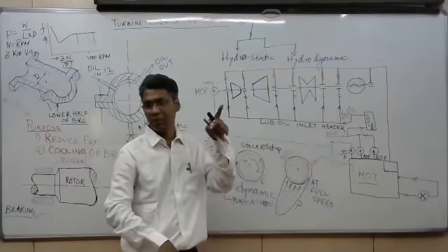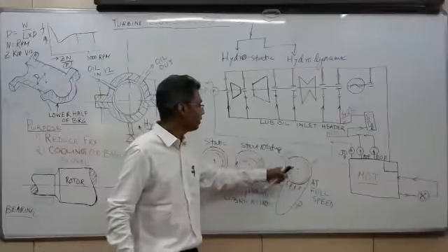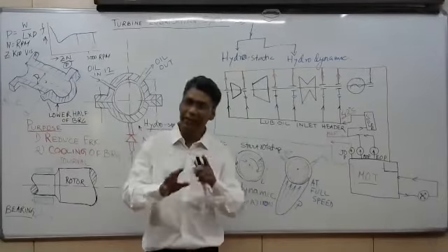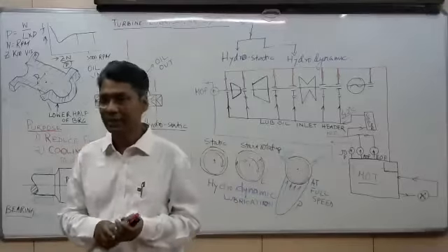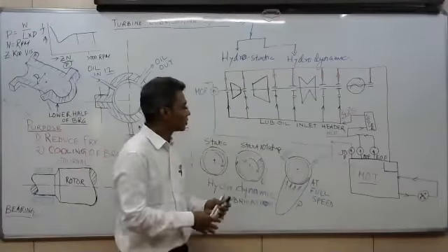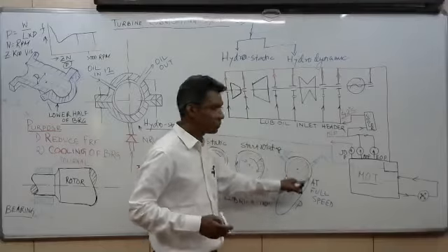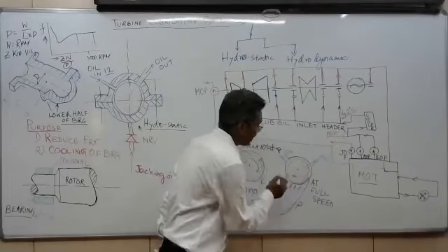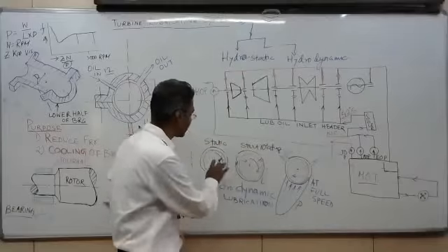It is giving pressure on both sides, but it is not allowing metal to metal touch between the bearing and the rotor surface. It never touches, and we are continuously achieving that. Once the full speed is achieved, due to the pressure distribution, it will shift in this direction, not in this. Initially, it will try to climb up.